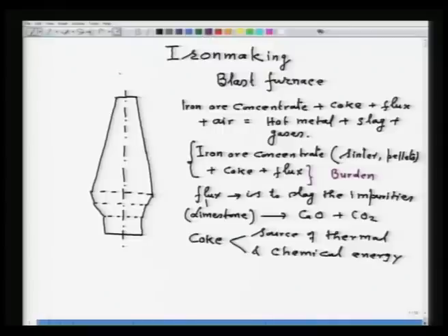The burden is charged from the top, and this portion is called the stack. This portion is called the belly. This portion is the bosh, and this portion is the hearth. The hearth has a tap hole for discharge of hot metal. Hot metal is heavier, and on the top you have the slag. It has tap holes for slag and hot metal.